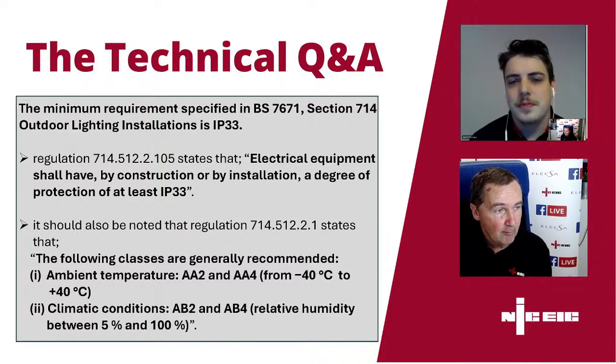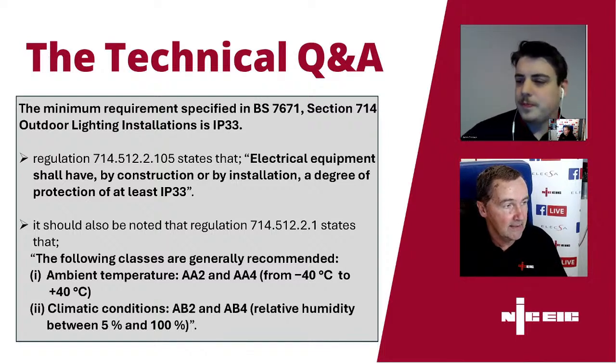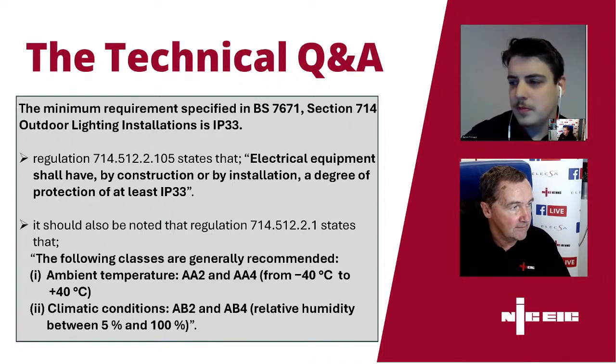So the Zs at the panel board itself is already a bit high before you even take into account the sub-circuit, so it's going to be very hard to get the reading down low enough with cross bonding to steel, etc. I looked at an adjustable RCD with settings up to 3 amp installed at the start of the sub-circuit, but it's far too risky with it being a call centre and servers involved, etc.